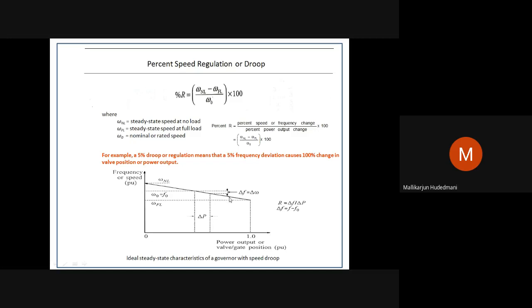Even though you are at 75% of the capacity of the machine, if there is no governor, we call it governor-free action. When there is no governor, naturally the frequency falls. It may be a subjected issue. Therefore, when it is a governor-based operation, the governor's duty is to see to it that such a drop in frequency is worked out immediately and brought to the steady state frequency.